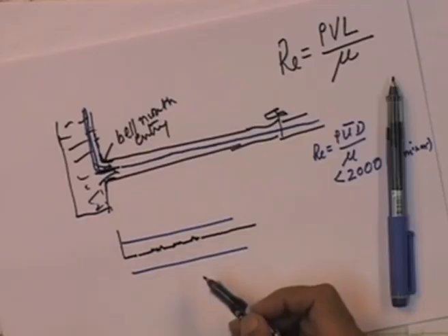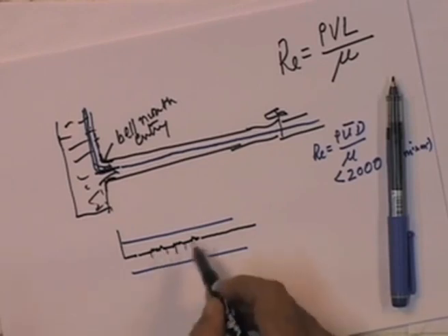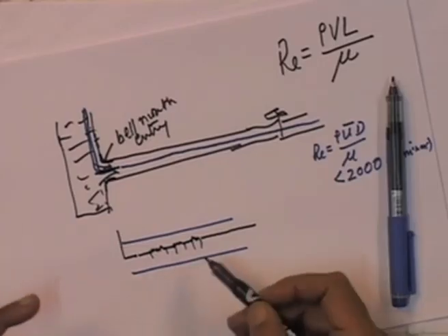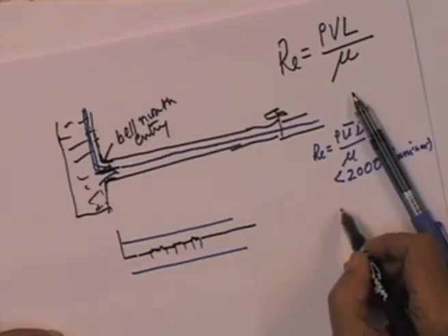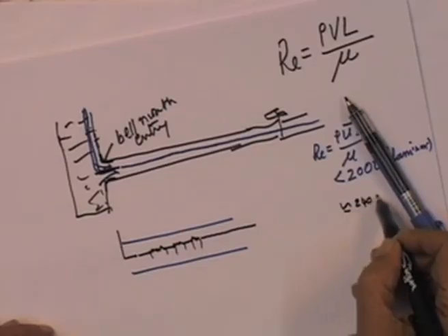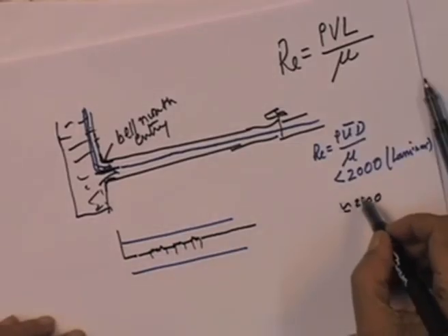So, in other words, he had a partly laminar, partly turbulent or unsteady flow. Locally, over fixed times, he would get turbulent spots or turbulent patches, if you like. And this state of affairs would continue till, say, up to about 2400 Reynolds number, or even 2500.